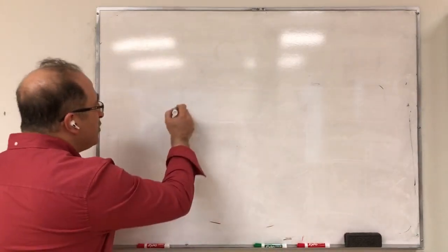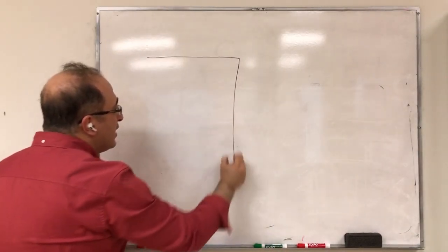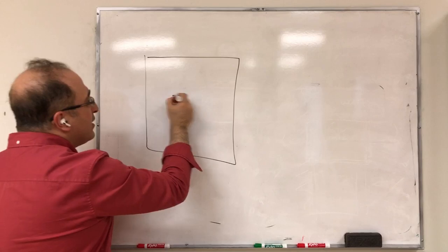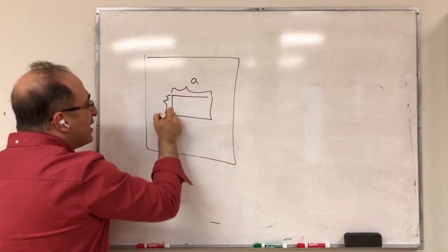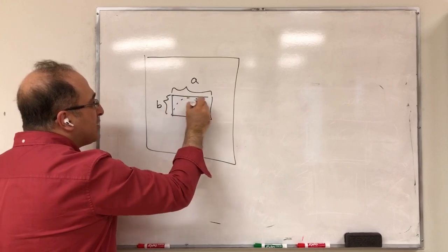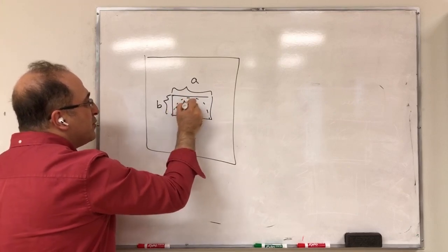Okay, so far we've covered the E-plane and H-plane of an open-ended waveguide antenna, and in general, the arbitrary aperture with the size of A and B. To just review that, we had essentially a PEC plane, and here we had an aperture of the size A and B, and here we had some electric field distribution.